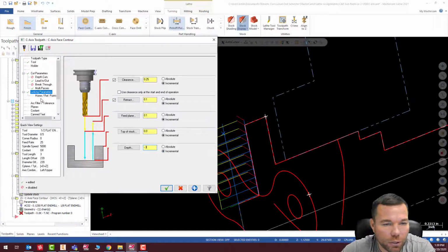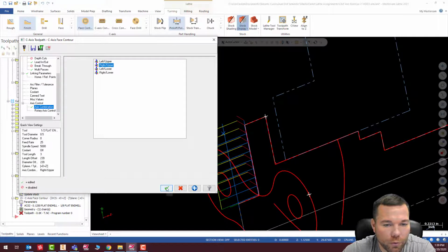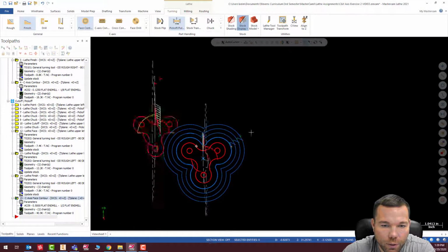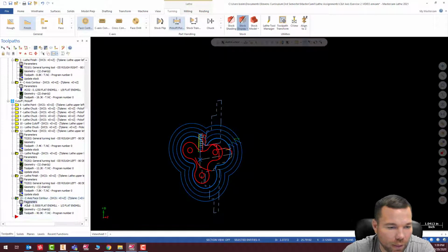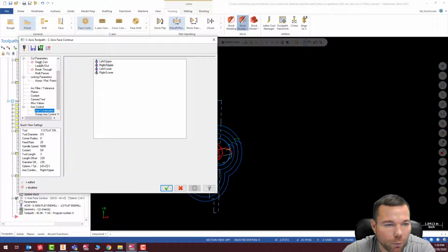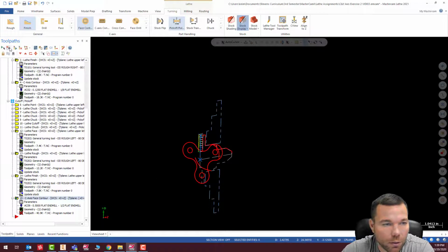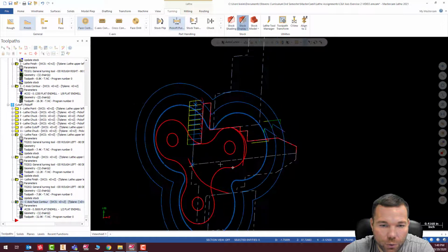That looks good. I believe everything there looks pretty good. Yeah, everything there should be okay. And axis control, upper right, check. And there we go. I get the feeling that I probably can take one of those multi-passes away. So let's make that 3. Check. Regen that. And let's go ahead and drill this thing.